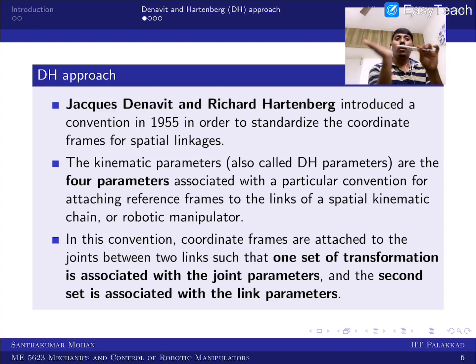So in the sense, this body would be attached with ground or one body, and the link would be progressing with another set of bodies. If you take any random link out of the manipulator, you can see that it would be associated with at least two other bodies, right? So these two bodies are associated through two joints.